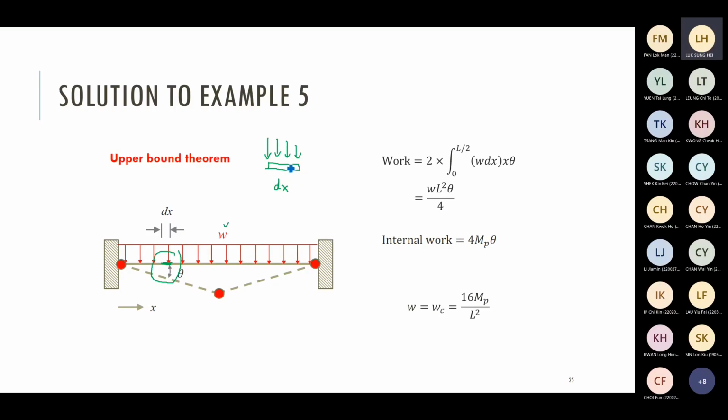For a small segment under UDL W, you may convert this force to an equivalent concentrated force. The equivalent concentrated force is equal to W times dx.